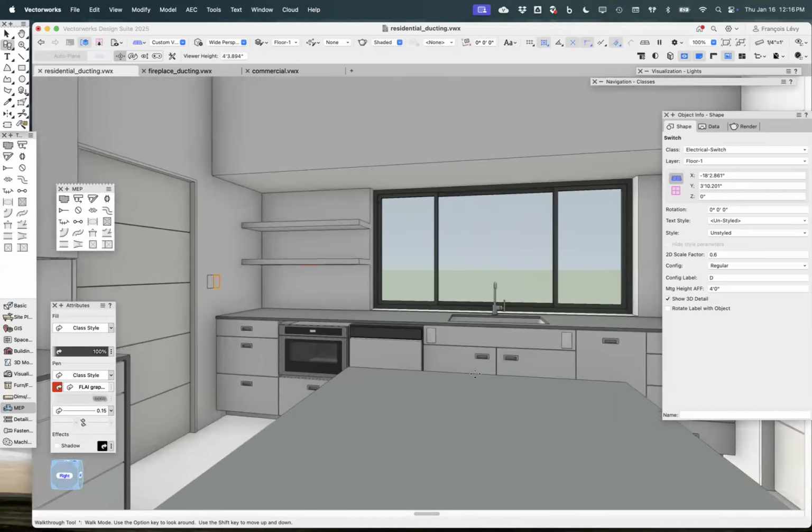So with kitchens and islands, we're always trying to work out how we're going to meet our IRC code requirements for access to outlets. We've sometimes done a 2-inch gap between the top of the counter and the bottom of the cabinetry, and stuck simplex outlets in those to meet those requirements. In this case, we've got a hidden panel where I'm showing the 2 outlets that go behind that flip down panel at the sink for access that the inspector allowed us. Not every inspector will let you get away with that.